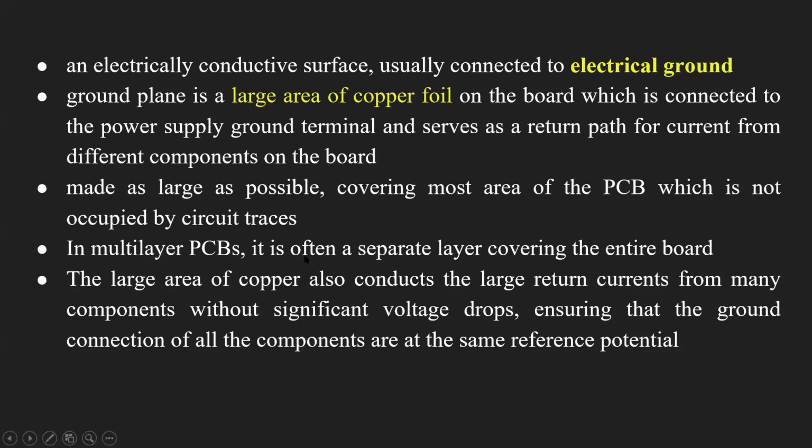In a multi-layer PCB, it is often a separate layer covering the entire board, as we had discussed three or four slides back in the 4-layer PCB scenario. The large area of copper also conducts the large return currents from many components without significant voltage drop. This is the main point why ground planes or power planes are situated in the PCB. So there should be no voltage drop in the PCB.